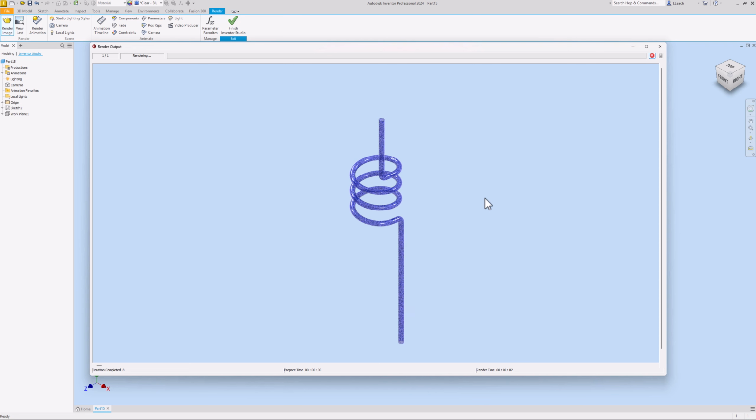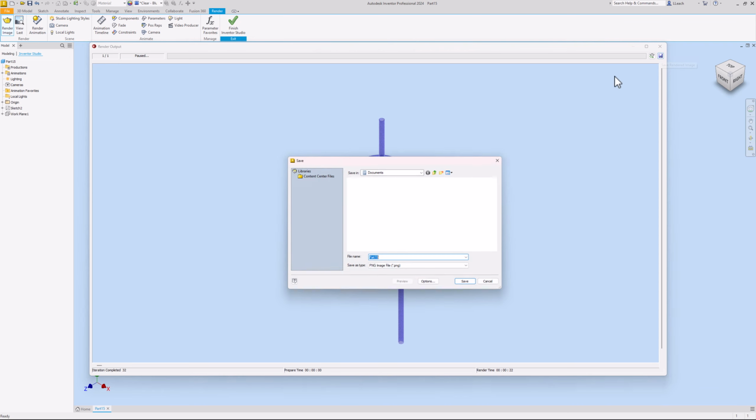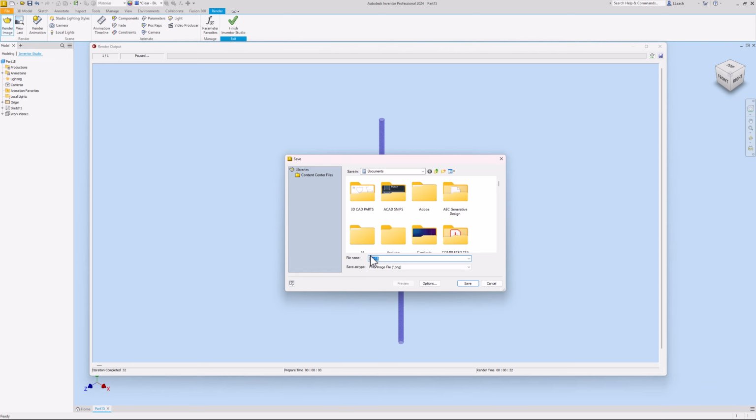Let this run continuously until you get what you like. Usually it's grainy with dots here, so I let it run until it gets rid of those little grainy dots. But if you want, you can grab a snap, come back. It should look pretty good. And then once you get what you like, hit the X up here. Click on the little Save Rendered Image. And I'm going to save it again just to make sure it didn't save before. I don't know, but render save 5, save, and that should be good to go.